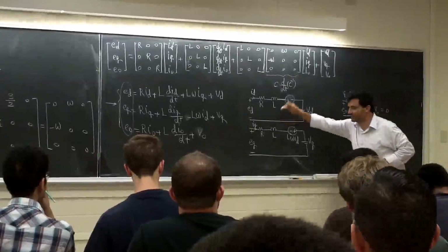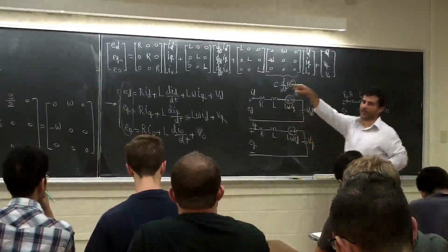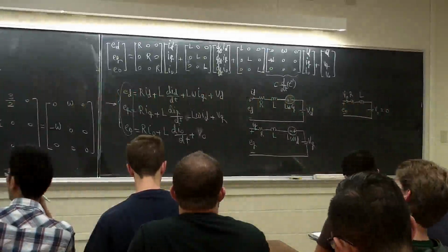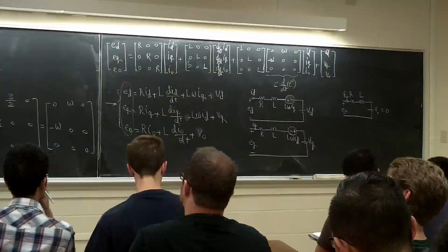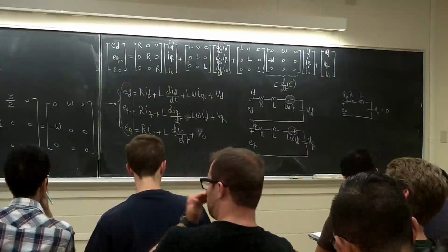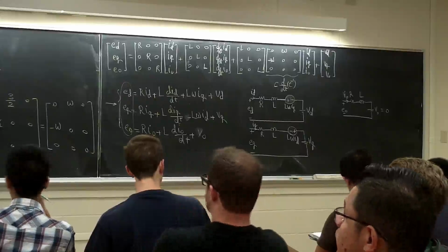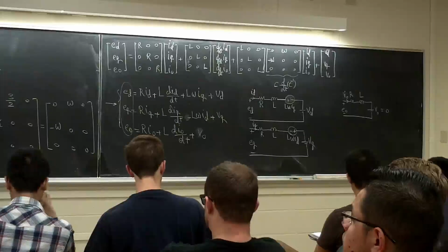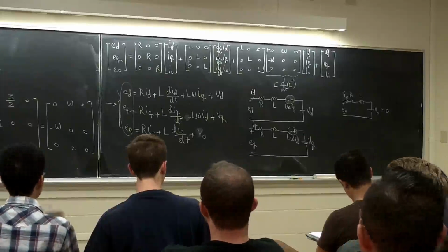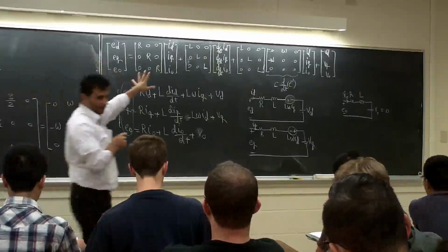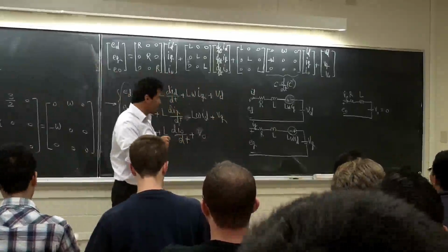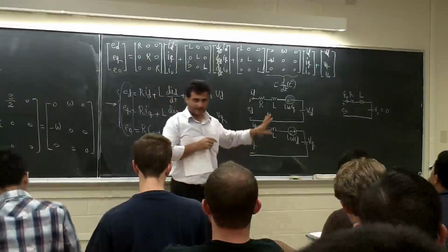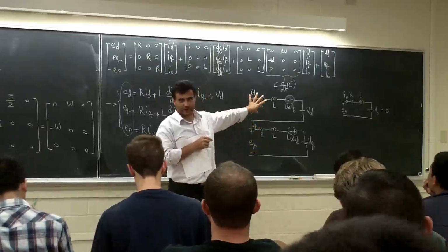Look at here. This is a DC circuit. It is not AC anymore. Think about it. This is the AC circuit. This is what I said. We got rid of the frequency. We don't have to follow this one anymore. We are going to only follow the peak value of this AC voltage or RMS value of that AC voltage. This is the advantage of the DQ. The frequency is gone, right? But there is a problem here. Let's look at it. This is a D circuit, right?